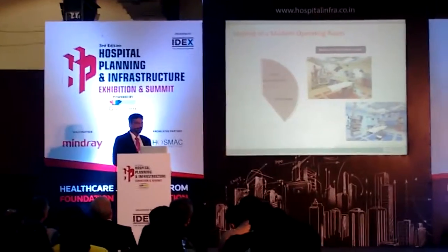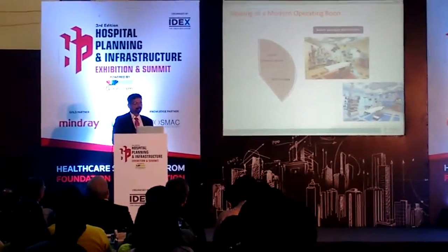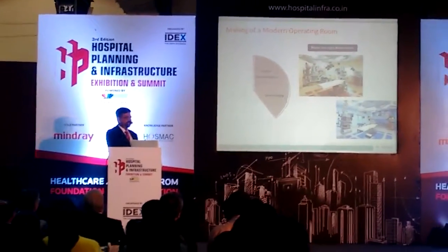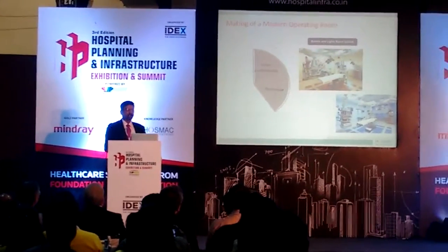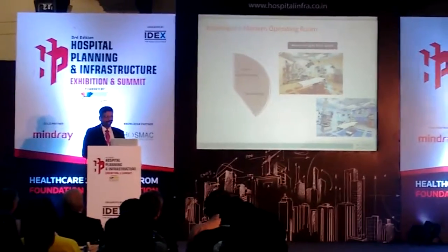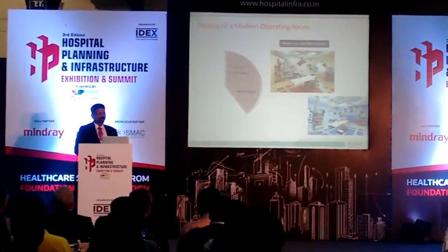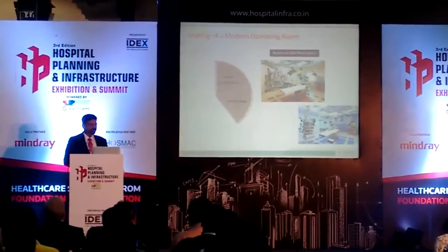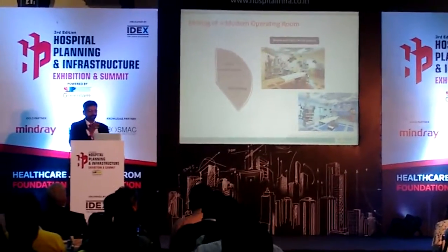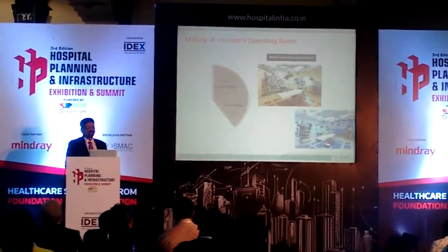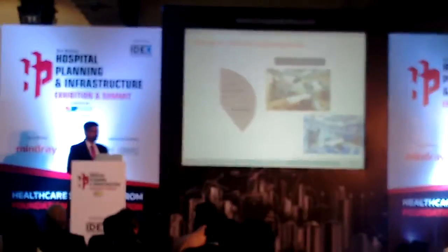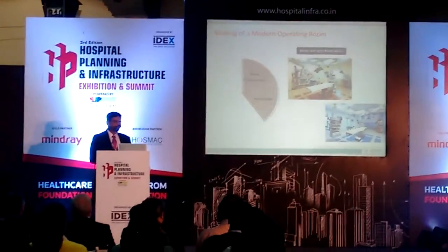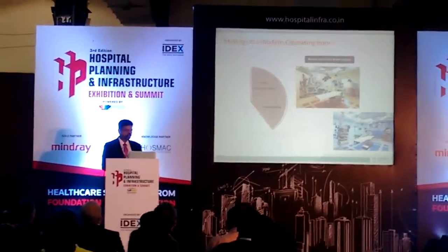We talk about laminar air. Again, we are not great advisors on laminar air, because HTM guidelines as against American guidelines talk about 25 exchanges. And if you start using laminar air with a 90 to 105 feet per minute velocity of air onto the surgical table, then the number of air changes jumps up to 80 or 90 air changes in the size of room you have, and it doesn't make any sense having that kind of volume of air being pumped into a room on a surgical site.